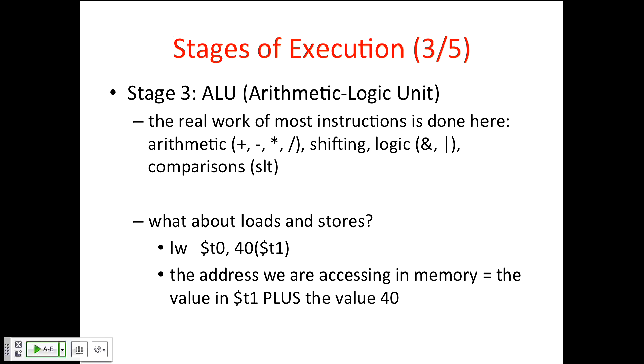So notice that the way the MIPS instruction set is designed, no instruction needs 2 adds. You're either an add instruction that doesn't touch memory, or you're a memory instruction that doesn't do any arithmetic, right? And that was a very conscious design decision so that you only need one adder in the system, in the ALU stage. It's either used to do the computing or to calculate the address for load or store.